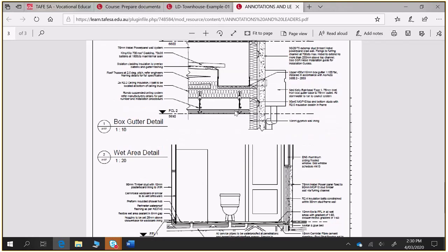Line weights and line thicknesses. So with Revit, you've got thick, medium, and thin lines. That's looking at it simply. There's actually the possibility for you to go in there and play with it and nominate whatever line thickness you want for certain things. For those of us who grew up drawing by hand or drawing on AutoCAD, intuitively or innately you get a really good idea of what line thickness you should use for what element. People who've grown up using Revit don't quite get that. I think that is one of the drawbacks of Revit, in that it doesn't teach people to think about those line weights. I guess it's a little bit beyond the scope of what I should be teaching or expecting in here. But if you get your head around line weights, once again it really helps with your drawing presentation.